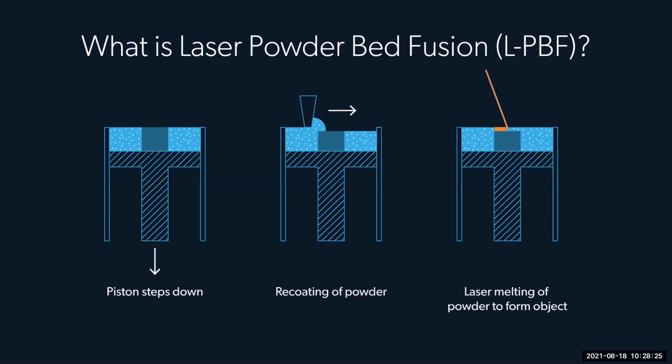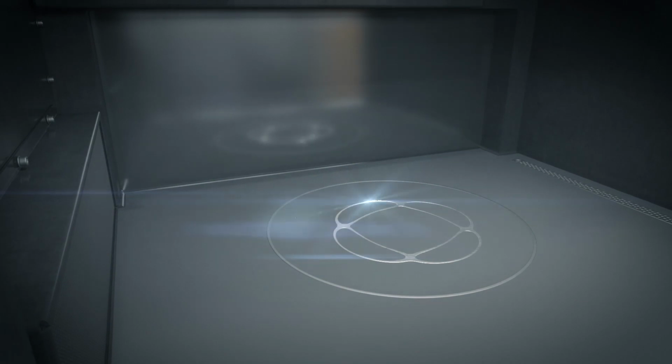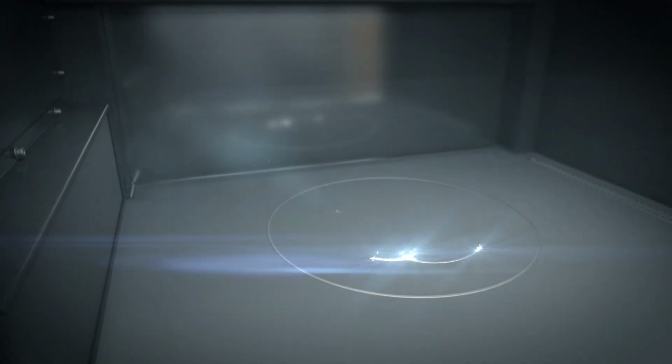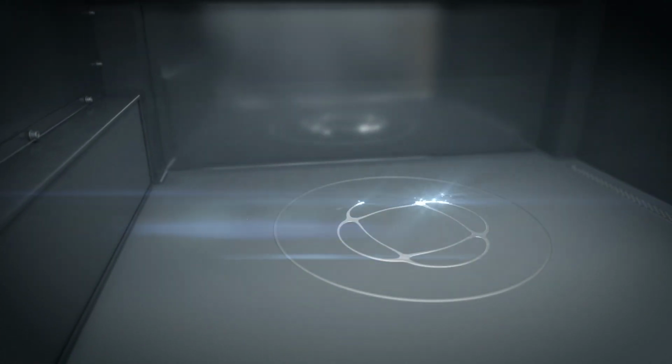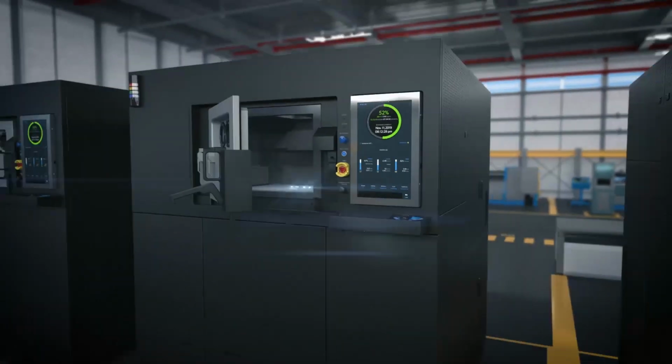The piston drops down a small increment, and then a recoater comes through and distributes a thin layer of powder over that build plate. And then a laser fuses material of the cross section of your part at that given layer. After that, the build plate drops down again, and it keeps going through this cycle over and over until it's welded up the entire geometry of your part.